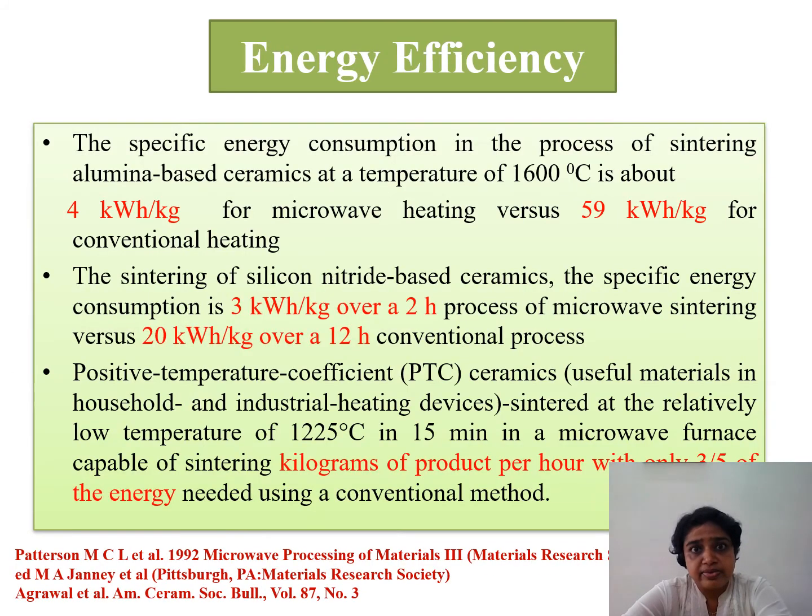Now let's come to the energy efficiency, because any technology is driven by the cost and effectiveness and how rapid it is. So the specific energy consumption in the process of microwave sintering of alumina based ceramic at a temperature of 1600 degrees C is just 4 kilowatt hour per kg. This is for the microwave heating system, against 59 kilowatt hour per kg for the conventional method.